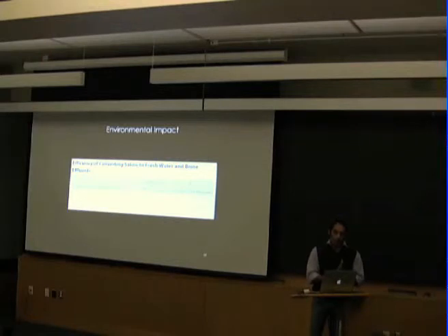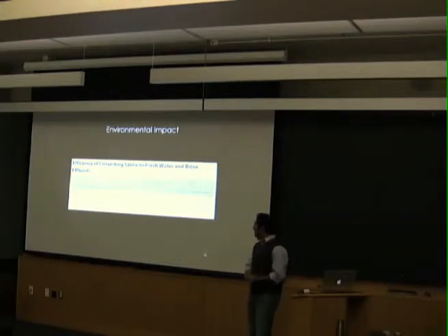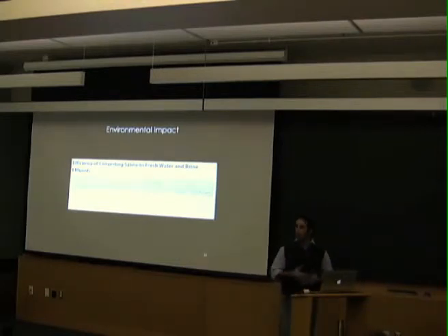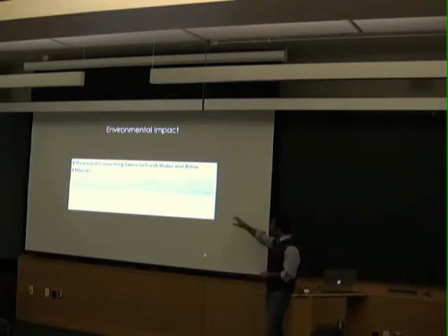In terms of environmental impact, for every cubic meter of water that you want to produce from a distillation process, you need 3 to 4 times as much source water. The rest of that is discharged into the environment as brine. For RO, those numbers are a lot smaller.